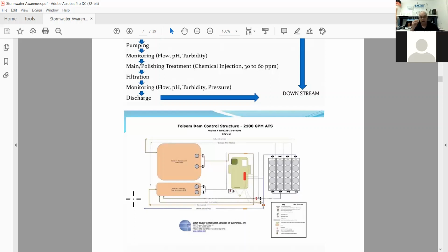Dewatering systems, on the other hand, are generally systems designed to remove contaminants by way of mechanical means. These systems differ from active treatment because they will use settling, mechanical filtration, and specialty medias in place of chemicals. At times, the turbidity level of the water flowing to the dewatering system may need reduction before the specialty media or to meet local discharge requirements. In that case, the dewatering system will become active in the fact that chemicals will be applied to reduce suspended solids. In this case, residual requirements will need to be met.